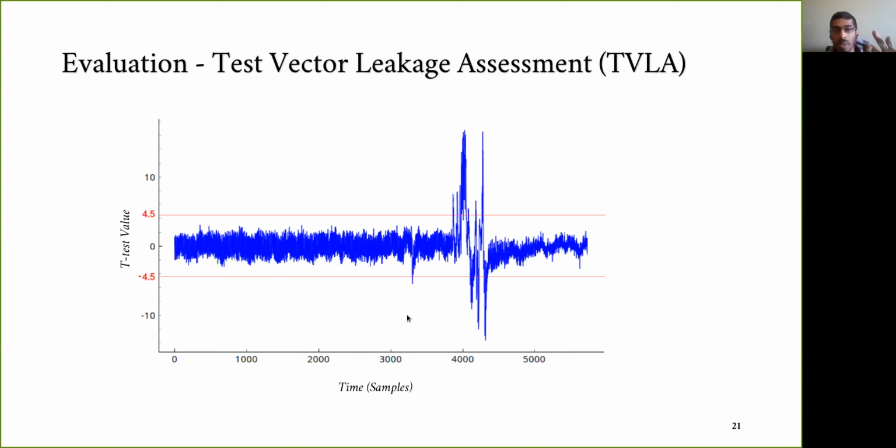So this is the graph that we can draw using the results that we get from TVLA. Each point that crosses the significance level counts. The significance level is 4.5 here, according to the p-values, and we can adjust it according to our significance for the p-value. This is the t value from the t-test, a statistical measure of how significant the leakage is.